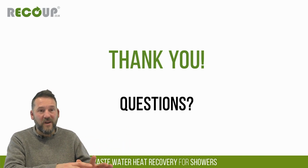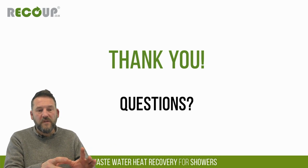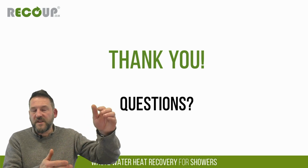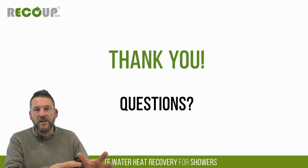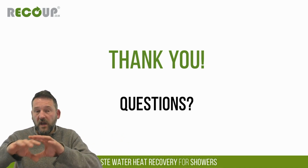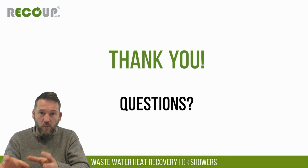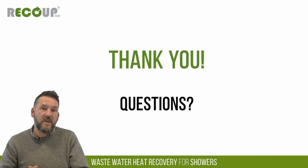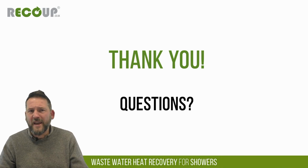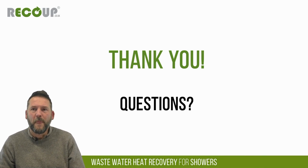And that generally is a lot more, because certainly with space heating measures, insulation, facades and things, it's a bit of diminishing returns. You can only throw so much at insulation before the cost outweighs the benefit. So moving on to hot water and reducing that energy through the hot water side gives you a quick win quicker, essentially. Hopefully that kind of answers without giving you a direct answer, but we can give direct answers based on projects.